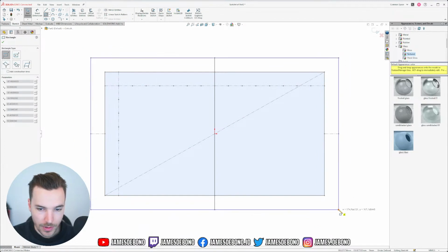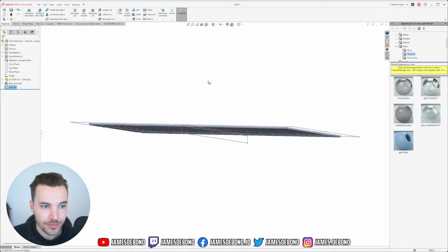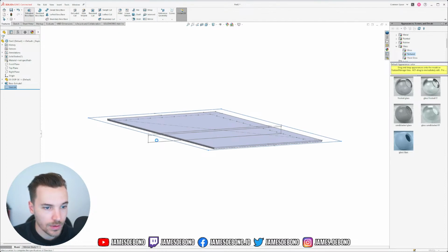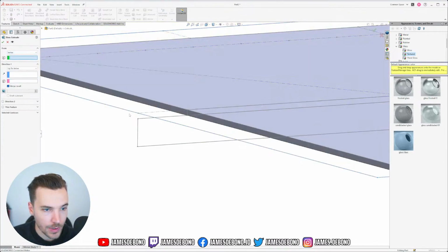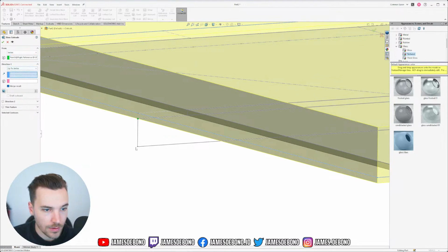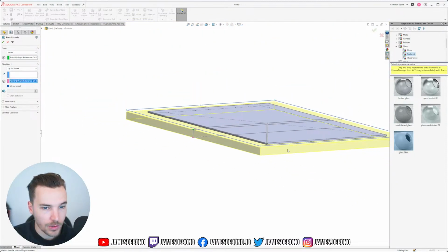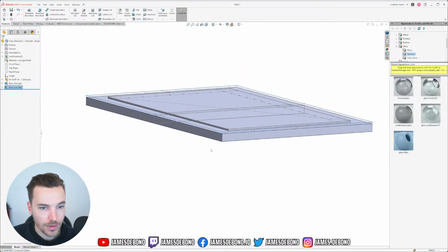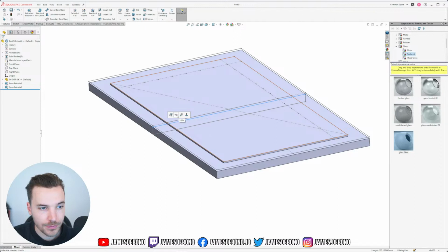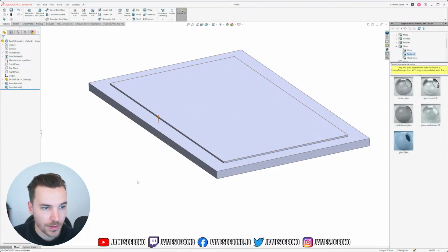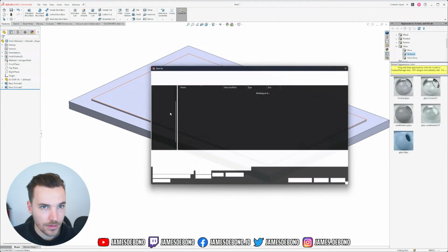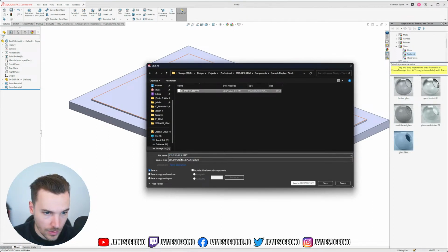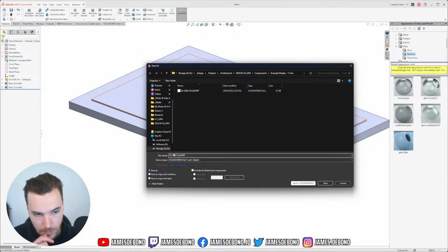Then I have the display body, which will extrude from here to here. Oops. And I'm not going to merge these bodies. I'm going to keep them as two separate bodies. That way I can give them different appearances. Okay. That's my display. I'm going to call it example display 1.